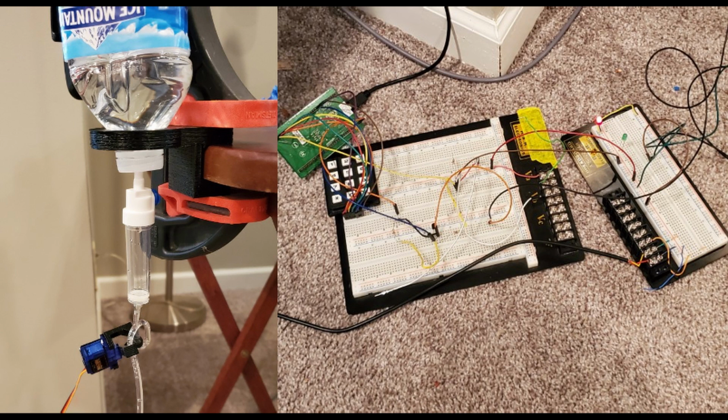This is the flow control and monitoring subsystem. This subsystem controls the flow rate of the IV saline using a servo motor that is controlled by an STM32 to crimp the tubing, increasing or decreasing the flow rate. A keypad is used by a nurse to change the flow rate, and when the desired flow rate has been achieved, the nurse can lock the system, preventing anyone else from changing it. To unlock the system, the nurse enters a password on the same keypad used to change the flow rate.